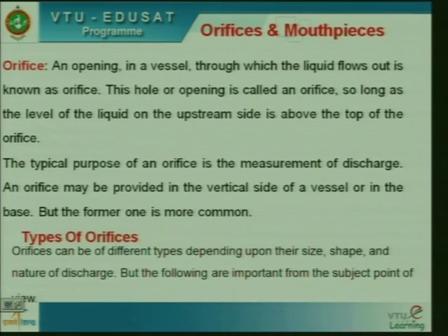If you look at the definition, an opening in a vessel through which liquid flows out is known as an orifice. Basically, in other words, if you make a hole or an opening in a plate, the hole behaves as an orifice. Now, what is the condition? Condition is very important. Look at the second sentence. The hole or opening is called the orifice so long as the level of liquid on the upstream side is above the top of the orifice. Very, very important. If you consider a circular orifice, you have a bottom edge, you have a top edge. See to it that the water level is always above the top edge of the orifice.